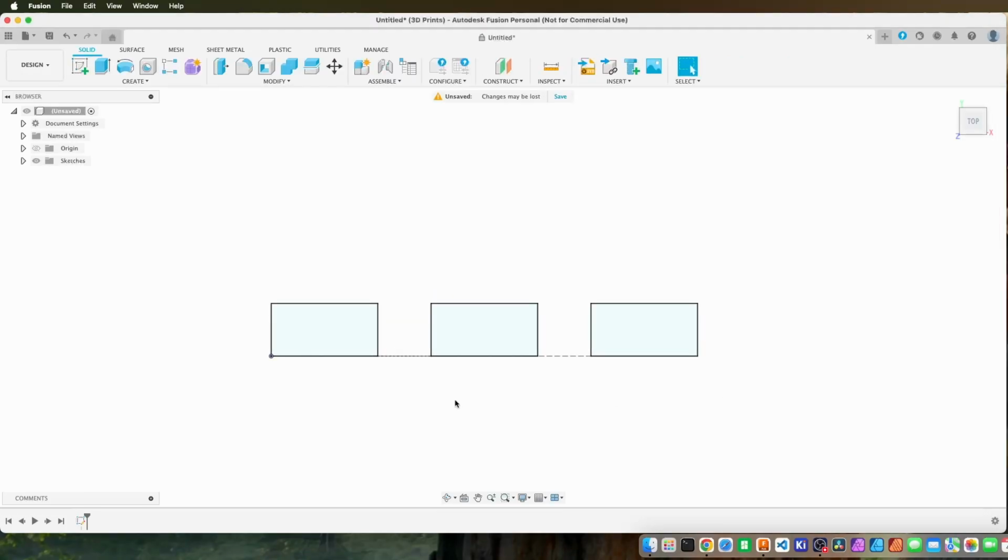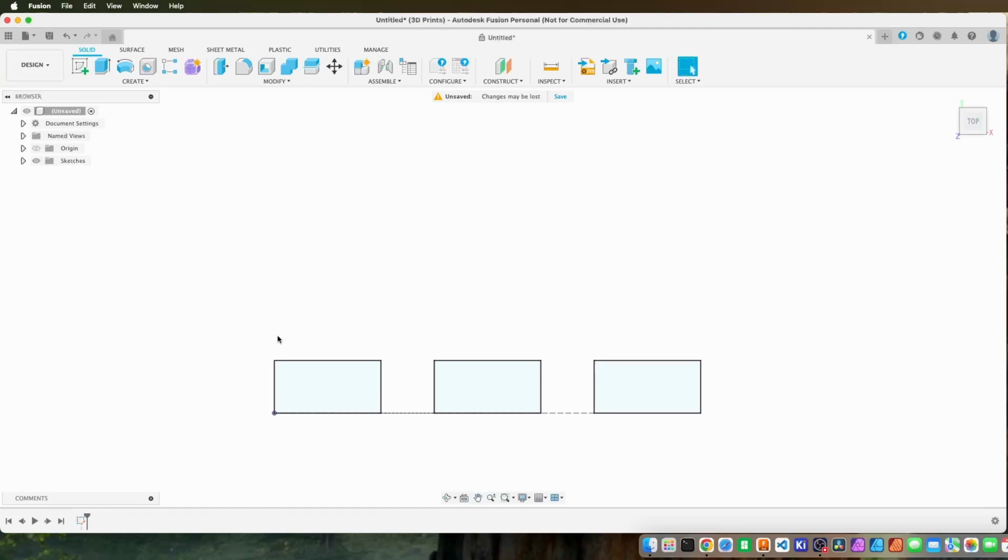If you want to have a go and learn a little bit more, just try to create a pattern of 3x3 rectangles with the same dimension, 25 between rectangles and 25 spacing here, and then the 6 rectangles being 25 by 50. Shouldn't take long, but that is a good way to learn Fusion 360.